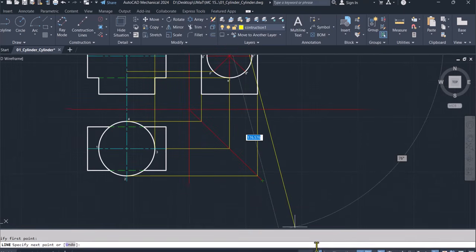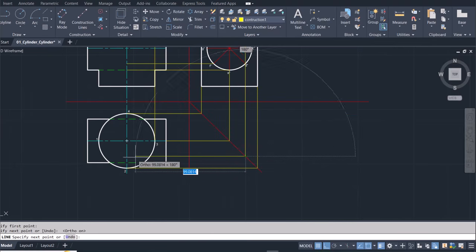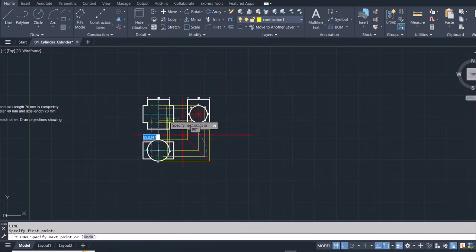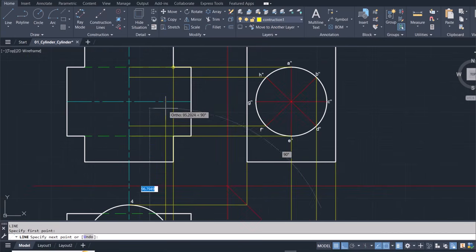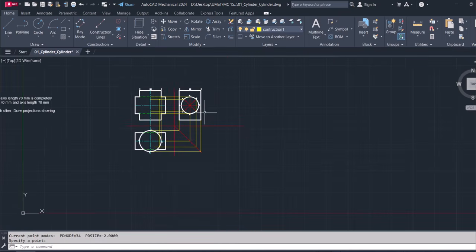So now I can go for B prime prime, draw it downwards until it hits the mitre line. Then obviously I go to my left until I hit the point of intersection, which is the circumference of the circle. And then I click that point and move it up, and then connect it to B prime prime, PO for point, and position my next point there.